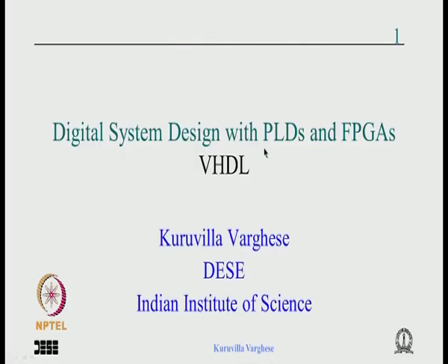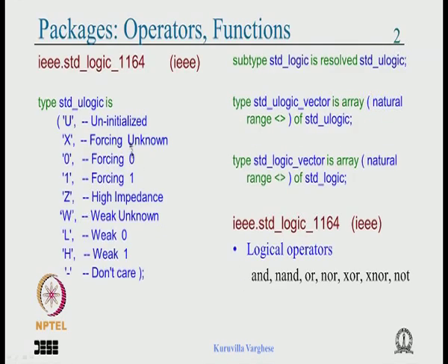So we have looked at the packages. The primary standard logic definitions are defined in this particular package. So you have standard U logic and standard logic vector, which is an unconstrained array.